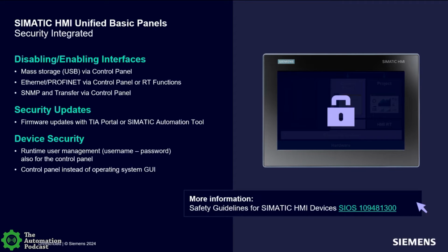the USB ports, if you don't have a purpose to have a USB port be active through the control panel or even in your project, you can deactivate those and it will never detect, activate, or even try to recognize anything plugged into those ports. So we have a very good security measure put into place to deactivate ports physically on the device. And you can activate them back up during runtime too.